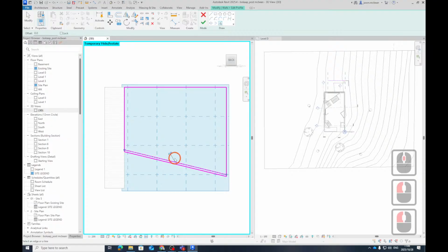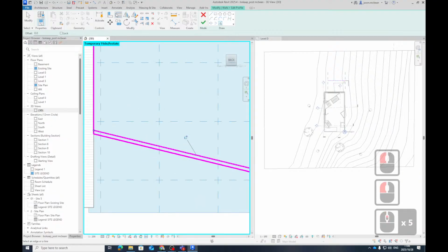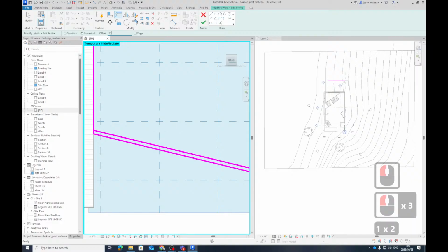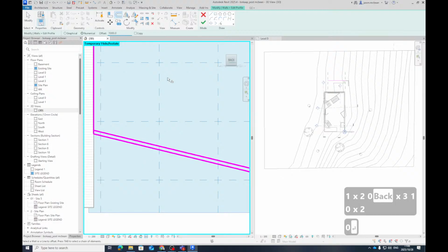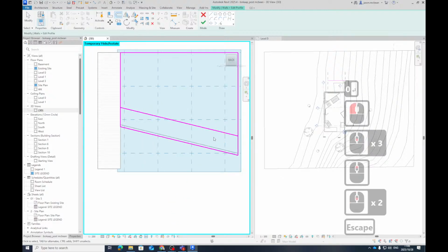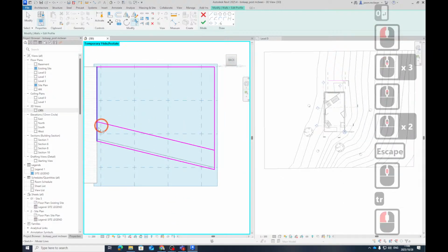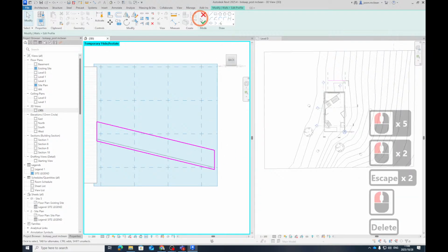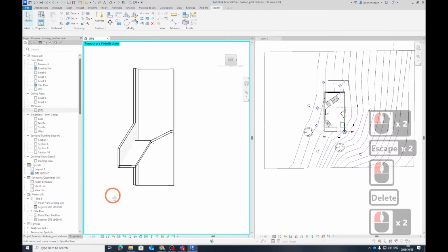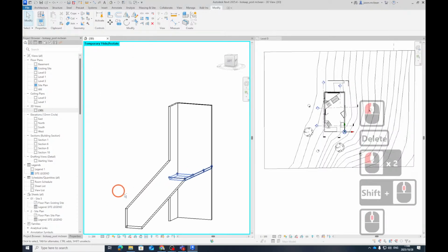I'm going to select the top of this, but now that needs to be offset by 900 or a meter, because a handrail needs to be a certain height. You guys learned that, hey? It's a meter. Part M, I think it is. Bang. Watch this. Now your wall is going to follow. Okay, yeah. Now your landing, it does the same.